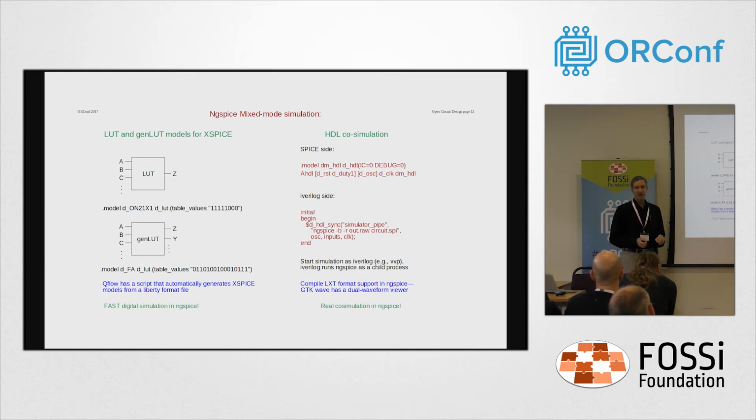That's doable. A lot of that is abstracting a lot out of your circuit, and often when you do that, you're actually building your models separately from your actual physical design, so that you then need an extra step of verification to make sure you didn't screw up anything when you rebuilt it outside. You've got a pad frame in your physical design. In your iVerilog design, you've just got a core and you're feeding signals directly into the core.